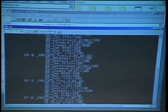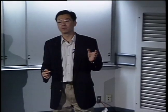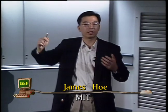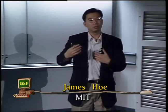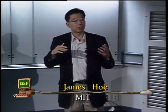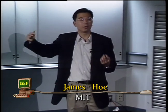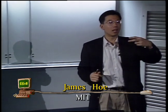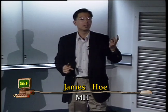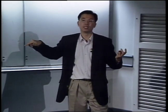What's happening there is my compiler actually does its own RTL optimizations. Synopsys does a pretty good job in doing RTL optimization. The reason my compiler does its own optimizations in RTL is that my compiler has access to the source code. I have access to high-level semantics embedded in the source description. So a lot of times I can figure out things easier or faster compared to Synopsys working on just RTL. For example, if you have two signals and they come from two conflicting rules, I know they will be mutually exclusive because my scheduling guarantees that. It will be very hard for Synopsys to infer the same kind of implementation by looking just at the RTL.